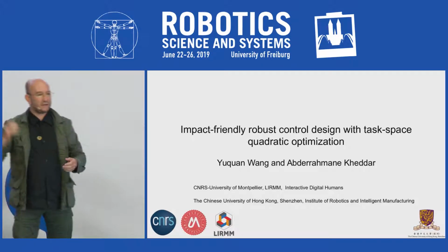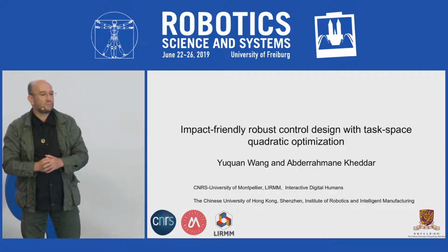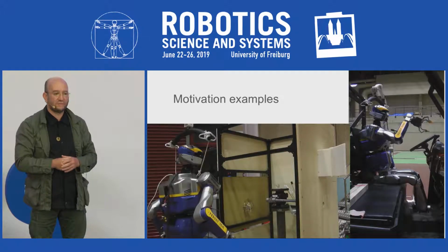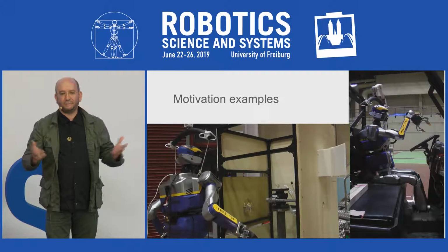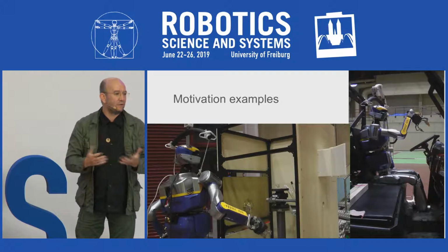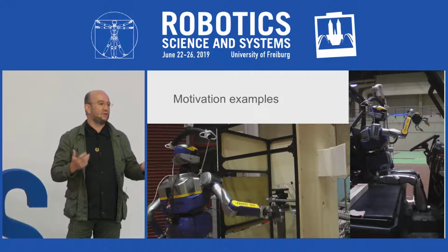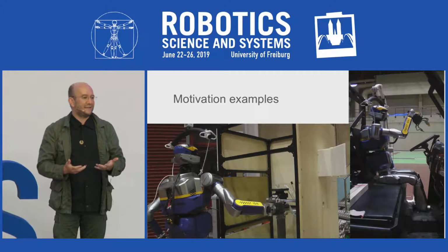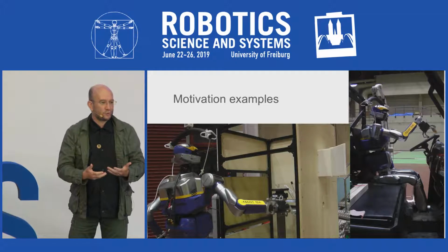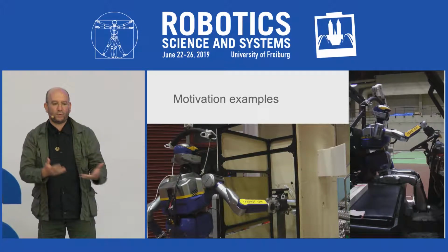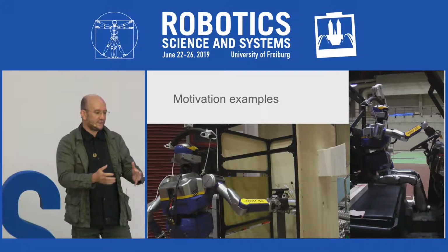Good. So in a few seconds, you will see a video of our humanoid robot, HRP2, performing a task for the preparation of the DARPA challenge. And you won't be surprised to see a robot having that slow motion. And there are 3 reasons for that. The first is that generally you have a perception that doesn't work at the closed loop control, and if you want to do feedback, you are obliged to deal with this frequency.